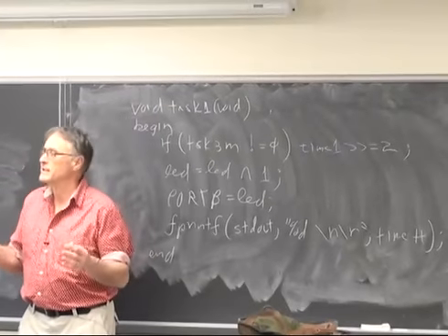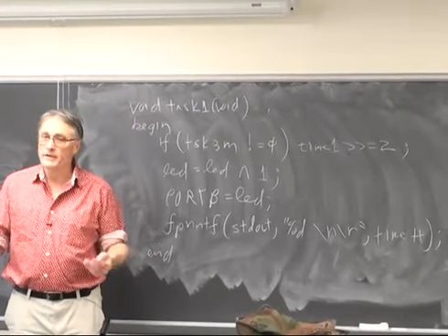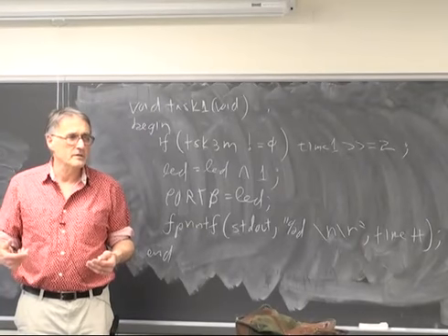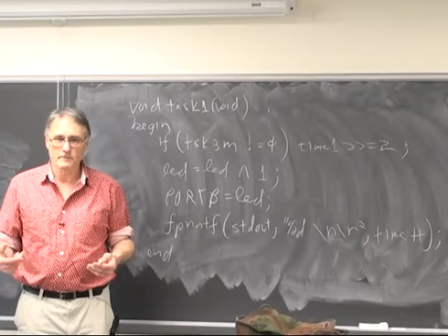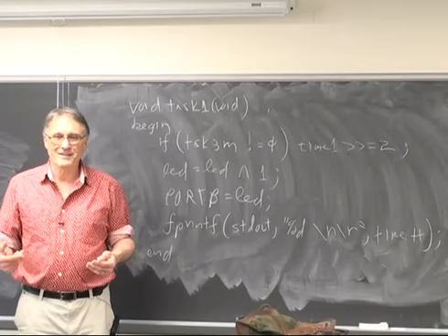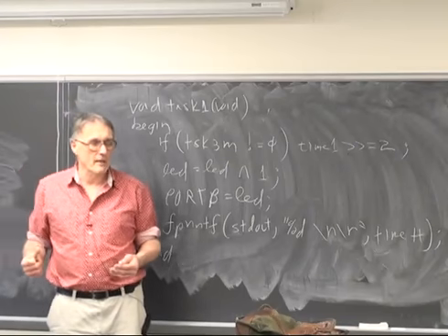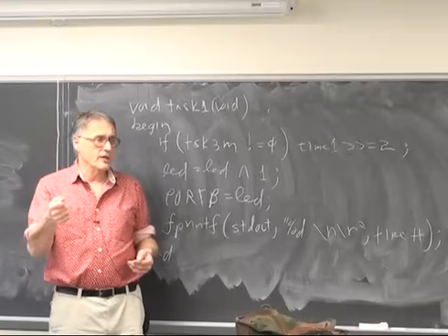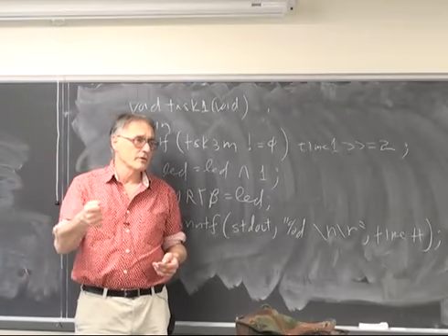I strongly suggest that you hook that to the programmer. The programmer on the STK500s uses a serial connection to the CPU. The TAs will have set up an example of how this works for your first lab. The other serial channel you need will have to be through a USB to serial conversion.